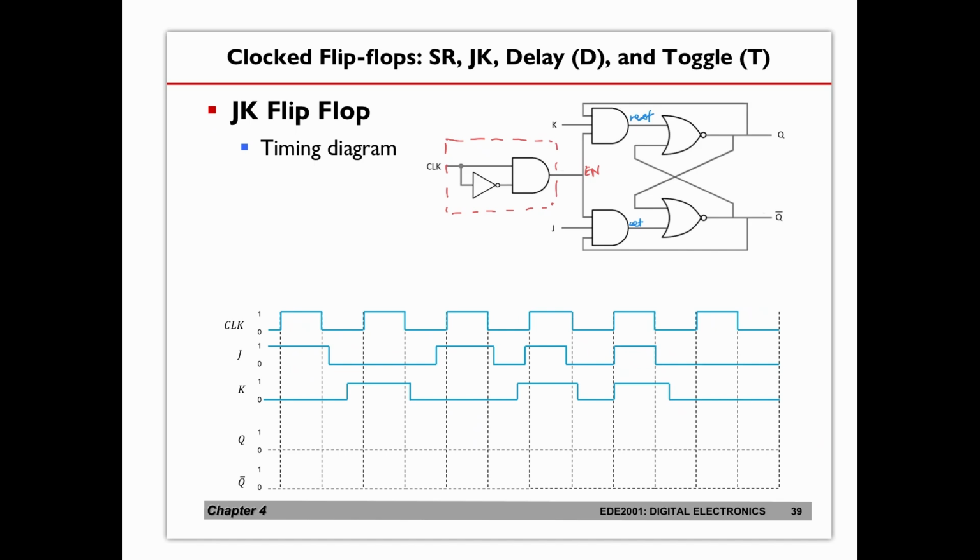The whole thing here is that we need to look for where you need to make a decision, and this decision point will be made at the positive going transition of the clock. So at these points, let's put the arrow here, is when you enable the flip-flop. We are only going to focus on any actions that happen at these locations. At all other moments, your flip-flop is going to be in the latch mode.